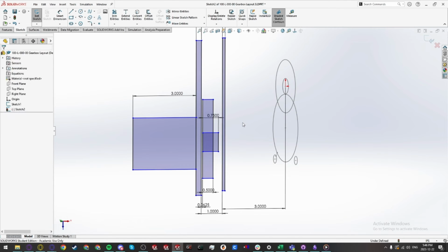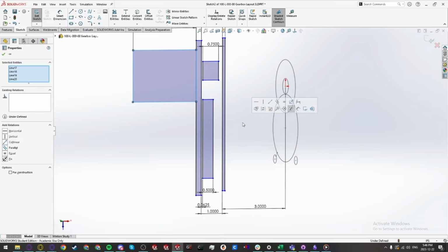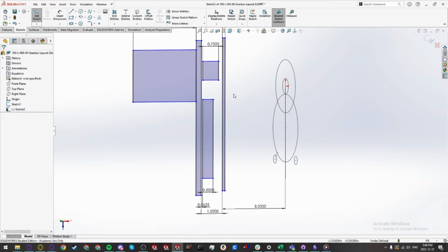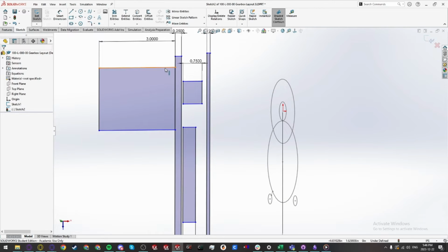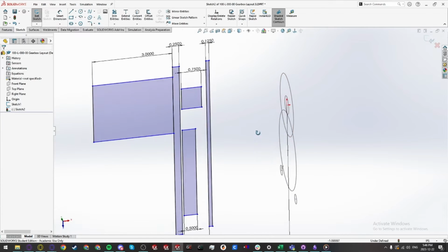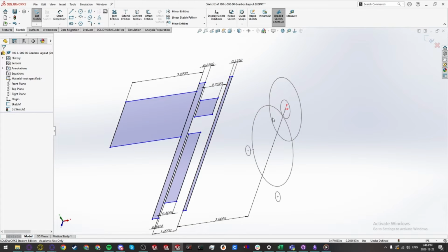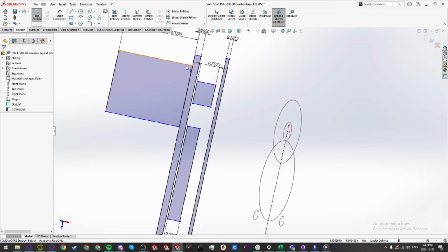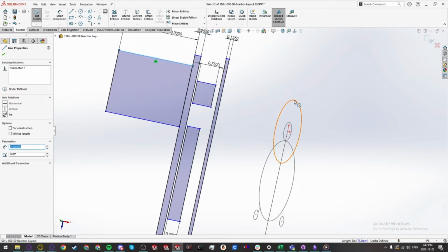That's not immediately obvious sometimes when you adjust things a few times. So what I'm actually going to do is add relations that reference the base sketch. Only thing is we can't do that quite yet because you notice that for the motor I don't actually have anything here on the base sketch that I can use in my relations.